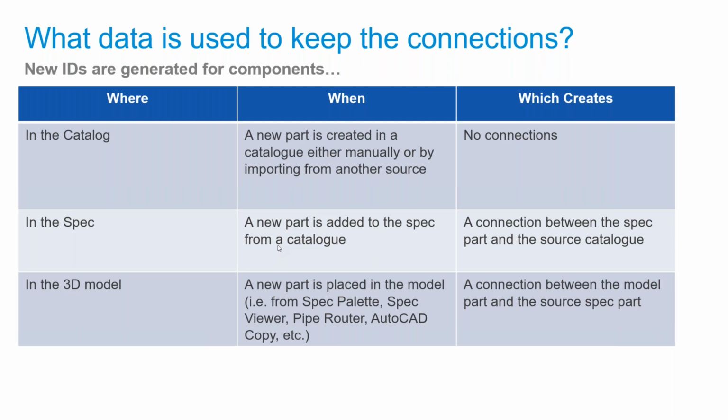Try to change some other properties in that part. If this doesn't work, maybe add a new family into the spec so the update is triggered. Just try to avoid deleting it. That's really key for the update of the 3D model from the spec.